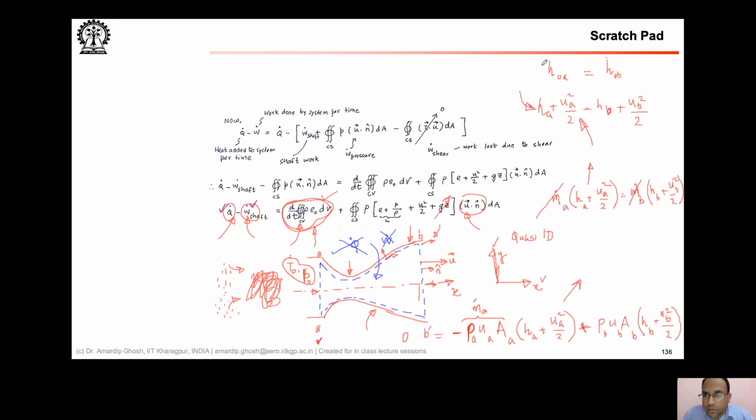So this is a very useful relationship, and you will see that this one helps us to find the temperature and the velocity, etc., in different parts of the nozzle. And you will see that this result is widely used when we look at rocket nozzles and we try to find, given T naught, what is the velocity at the exit, etc., using this particular formulation.